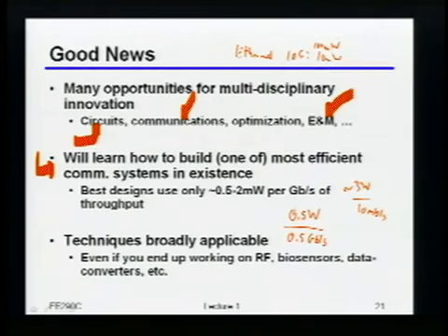10 watts. Yeah, okay, so it turns out it's typically about 5 to 10 watts or so. So 10 gig Ethernet, this is a wired standard, so this is a link. Again, that's not to say that link guys are always great and wireless people suck. You can do good and bad things, obviously, in both. But this is telling you that there's a very nonlinear trade-off. Why is it that 10 gig Ethernet is like this 5 or 10 watt kind of thing, whereas my link that's just talking from, let's say, my processor to my memory, or even on these backplanes, is maybe only 10 to 20 to 100-ish milliwatts, okay?